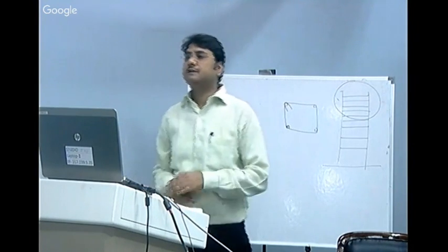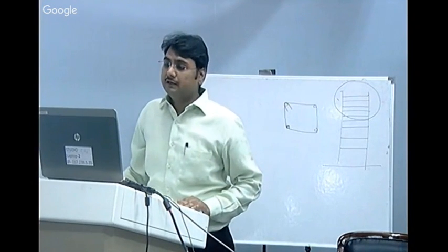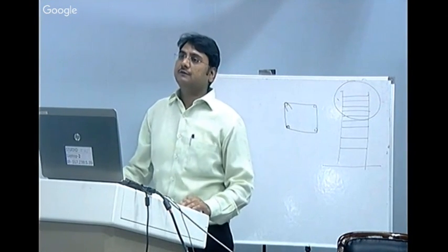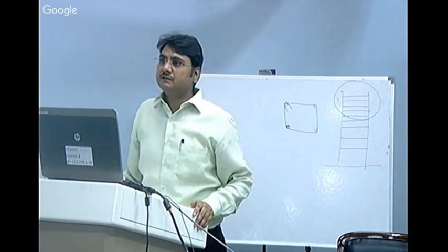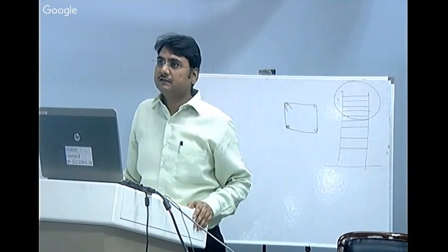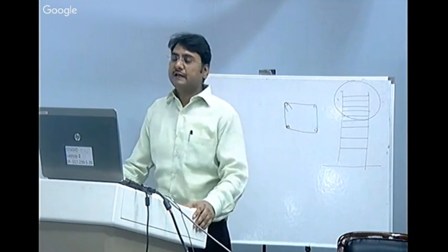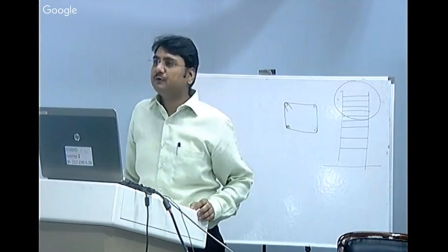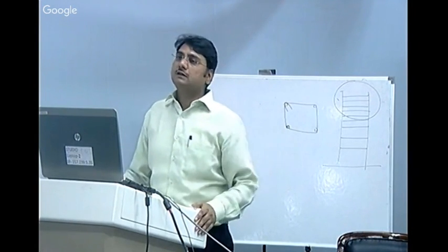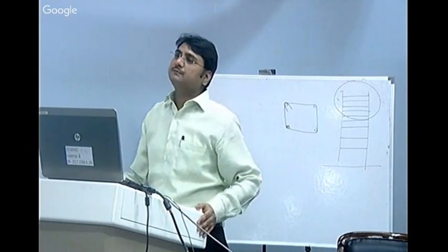So here I'll explain what we did. We did some research, and we have made one interlinked block masonry system with viscoelastic energy dissipator links. We have developed this completely new technology for load bearing type of structure. But still the research is on. We are also testing this technology for the framed structure.